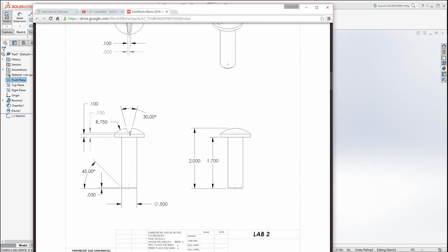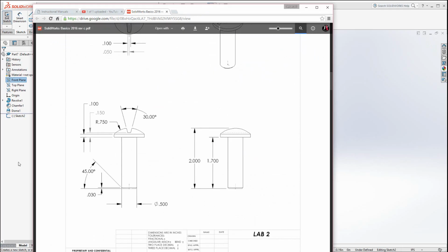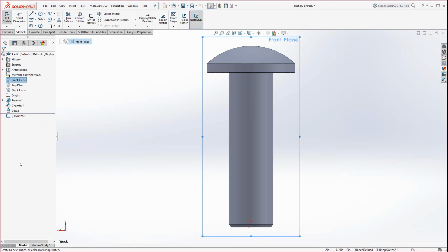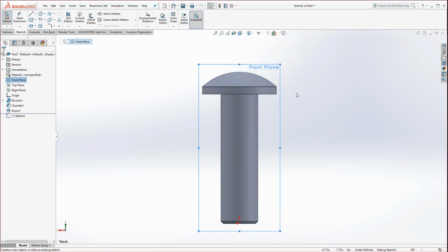So in this case, the base of the cutout is 0.15 from the underside of the head of the bolt. And then it's 30 degrees symmetric on both sides. I know the drawing isn't the best, so bear with me. And we're going to put that in there. So this is where we could use our mirror tool. Notice for the bolt, I did not mirror it. The bolt didn't need to. The Revolve took care of that.